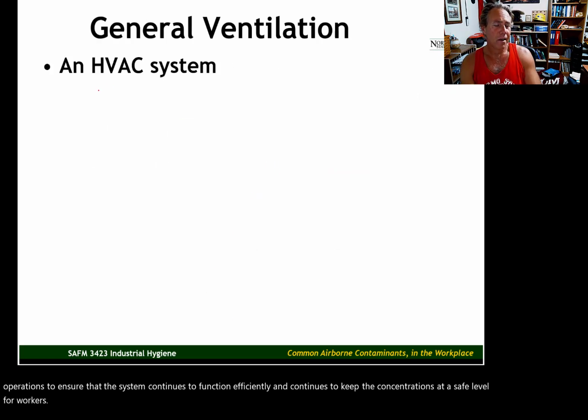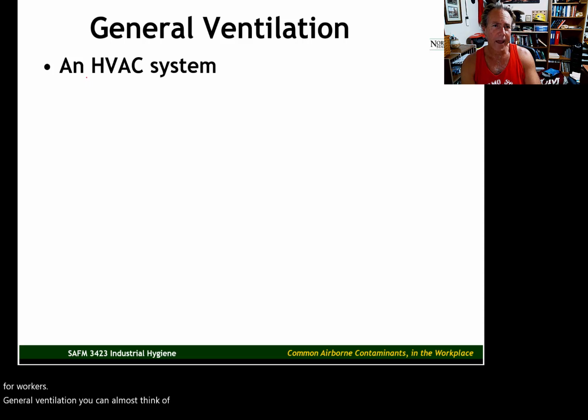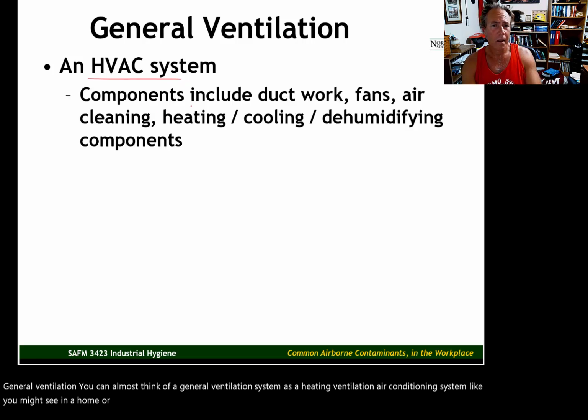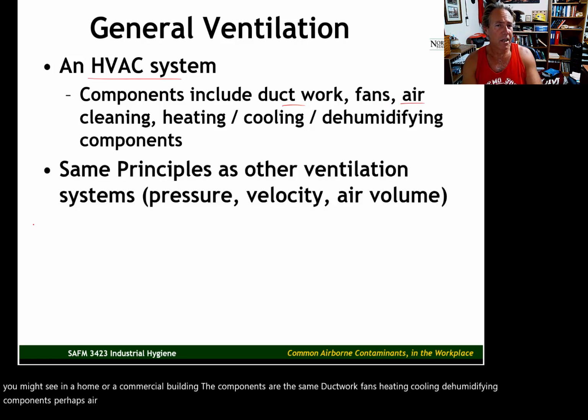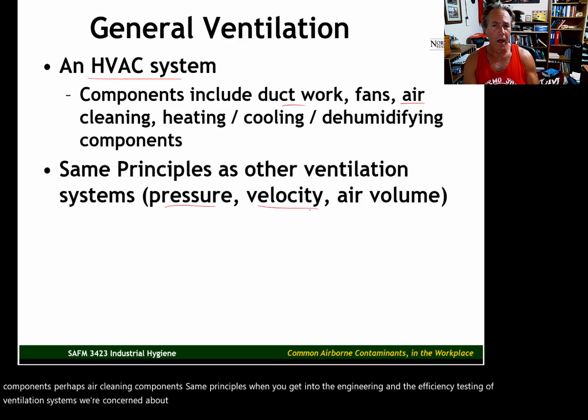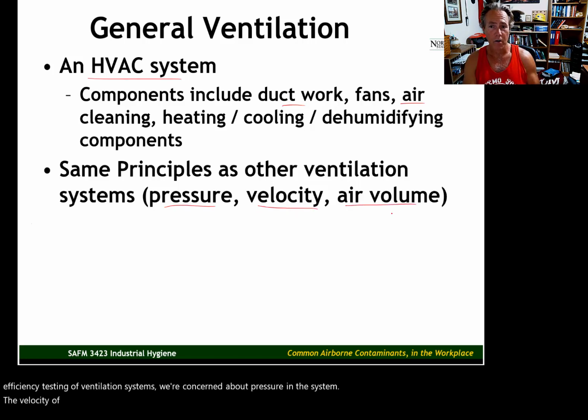General ventilation. You can almost think of a general ventilation system as a heating, ventilation, air conditioning system like you might see in a home or a commercial building. The components are the same: ductwork, fans, heating, cooling, dehumidifying components perhaps, air cleaning components. Same principles. When you get into the engineering and the efficiency testing of ventilation systems, we're concerned about pressure in the system, the velocity of air movement, and the volume of air that's being moved through the system.